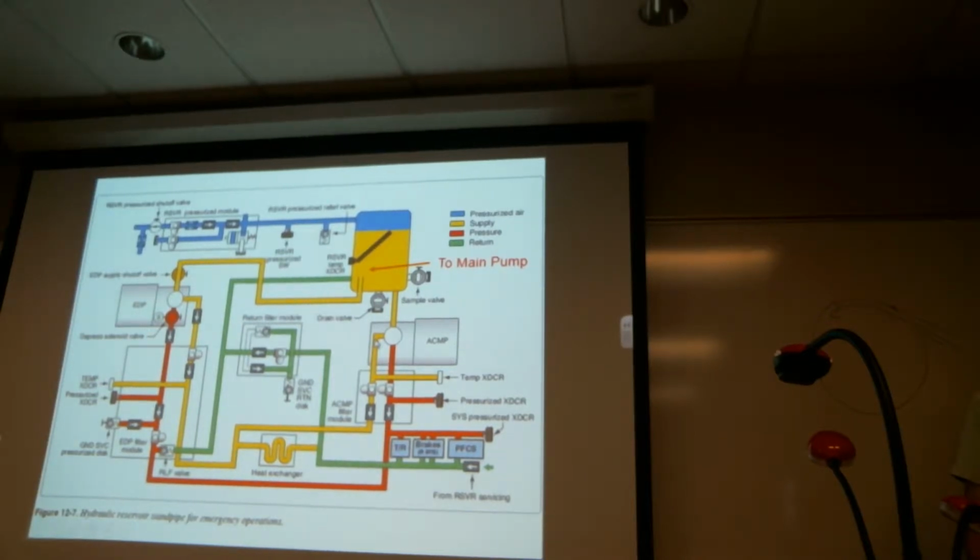It's for circulation of hydraulic fluid that eventually will return itself back to the reservoir. And they call that a case drain. Sometimes it'll go to a heat exchanger, but ultimately it ends up finding its way back to the reservoir. So this goes along with the cooling circuit that they have in the hydraulic system.